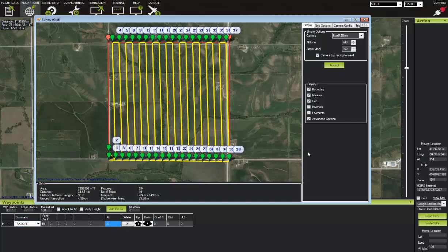So for example, the Zephyr 2 flies for about 60 minutes, while the Zephyr 3 can fly for about 180 minutes. Knowing that the aircraft flies at an average of 10 meters per second at normal cruise speed and needs to fly a distance of 31 kilometers, given the approximate wind speed, you can roughly estimate how far you're going to be able to fly with your UAV given the desired flight mission suggested.